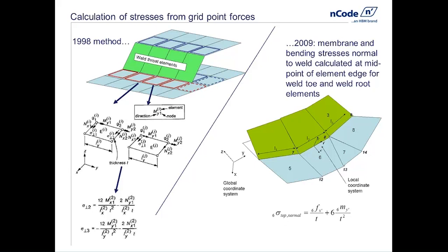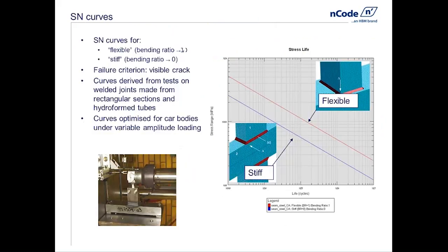Again, we're calculating structural stresses. These are stresses that don't necessarily occur anywhere in the model, and are definitely not the actual stresses at the weld toe. But they are the stresses that we're going to utilize as a damage parameter. They were selected because they show a fair insensitivity to things such as mesh distortion and mesh density. To go off and produce the damage curves for this is a several-step process.